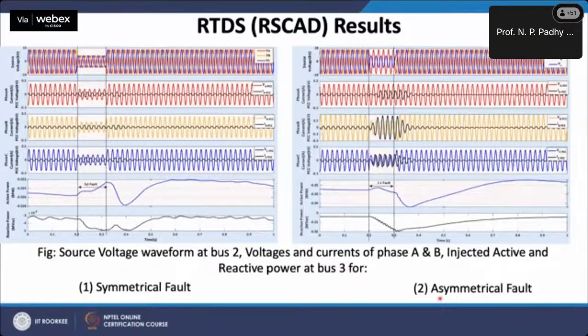In order to test the behavior of the DFIG wind system at the most severe unbalanced voltage, the phase to phase asymmetrical fault is considered in the analysis, as the phase to phase fault results in a larger negative sequence component in the voltage than the single phase fault for the same depth.